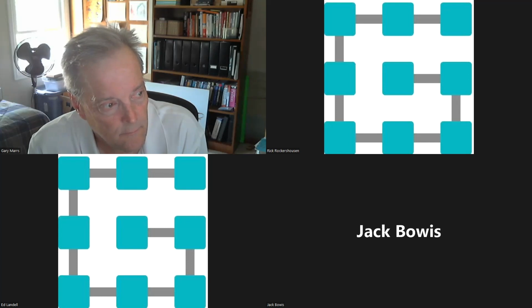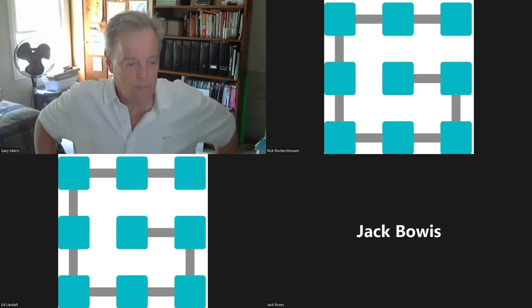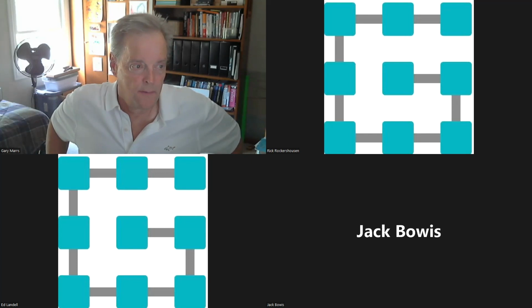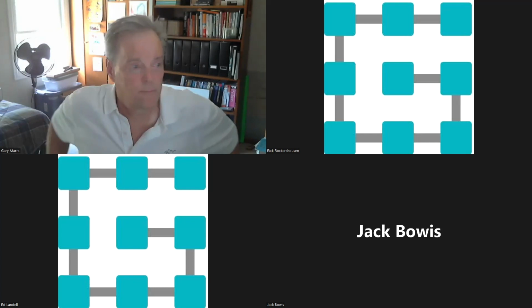Great, good to know. All nodes on the network have to support CAN FD. If any of them don't, then you can't use CAN FD communication. Correct. But maybe that could be the issue. Yeah, it was eventually solved with a software update on our CAN keypad.